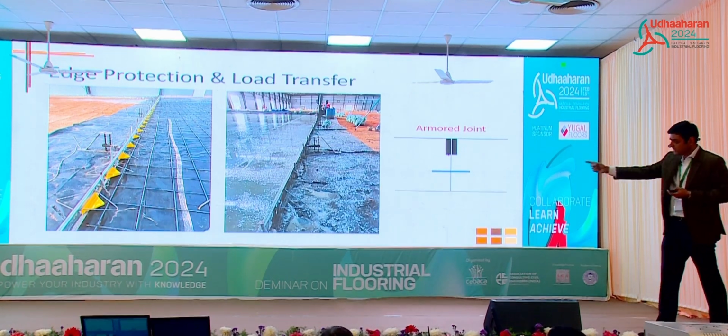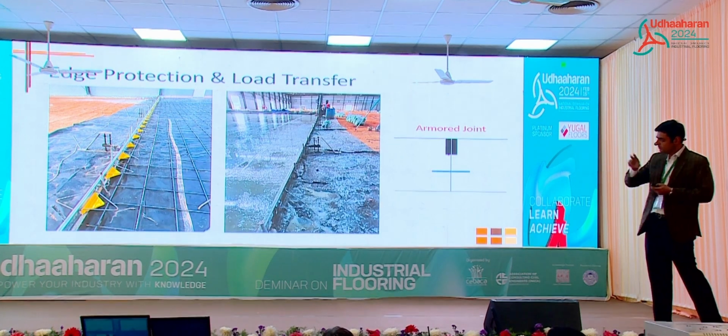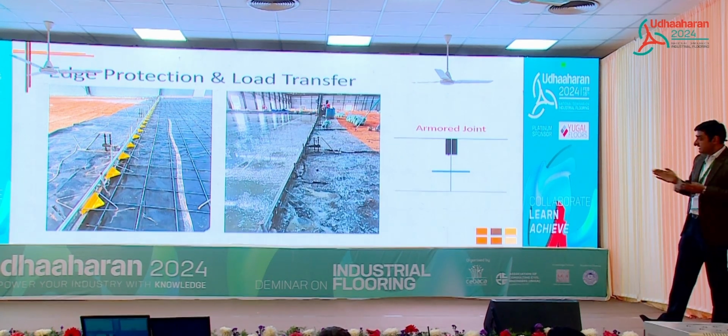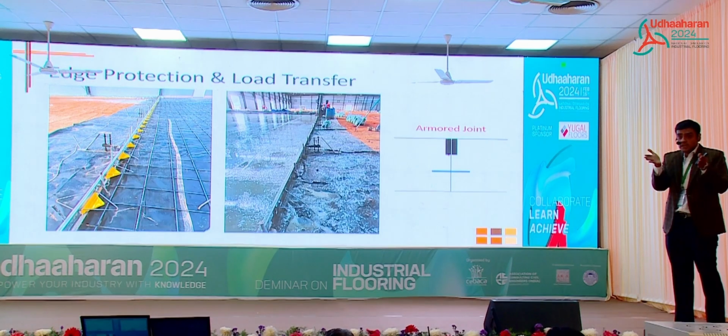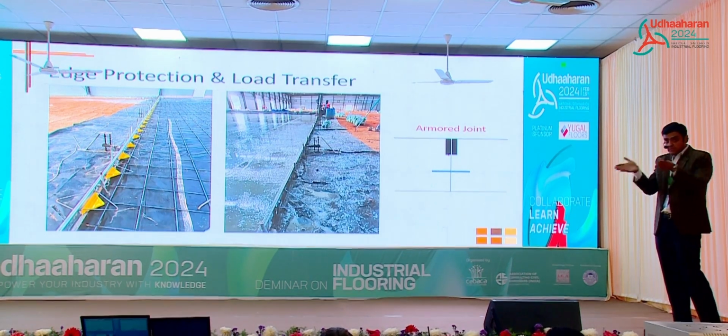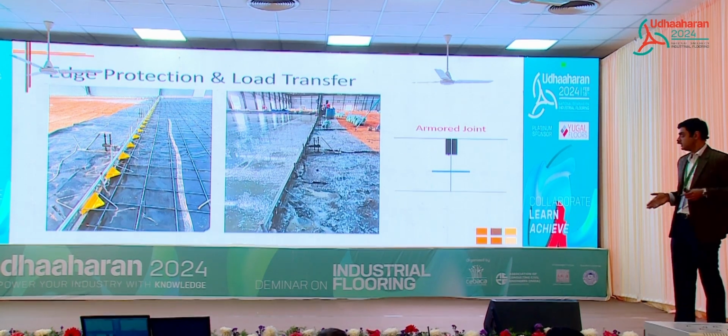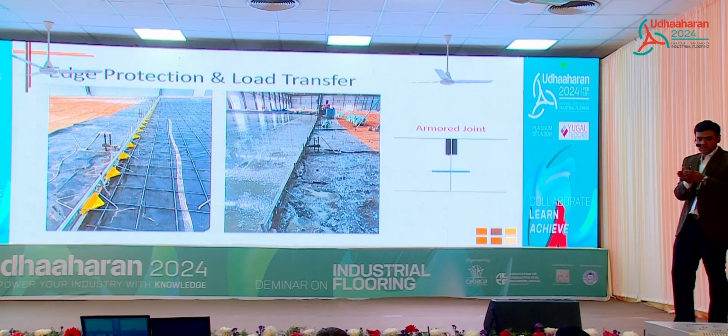And then in this joint, you see a very thin line running between those two strips, right? These are two strips that will open up. So if you're dealing with a situation where the concrete shrinkage is very high, where the sand is very fine, what do you do? You actually reduce your panel size, because your panel to panel shrinkage will reduce. This joint will open less. But as long as you have an armored joint opening of about 10-12 mm, you're still fine.